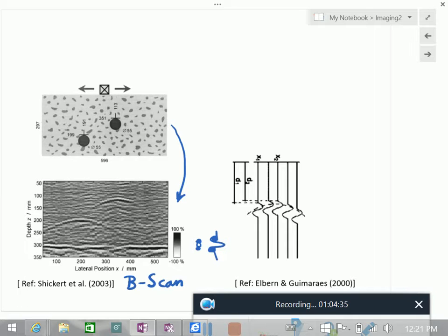One thing is the lateral resolution is very poor. So you have these wide hyperbolas where you have only a hole like that. And then also, you look at all the structural noise you have. One thing Jiang said, which is very valid, is if they're very close to each other, there would be no way to find out where they are. So your resolution is limited.